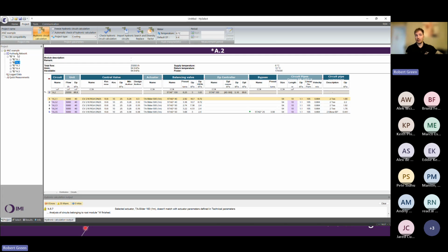Open those 2, close another 2, and prove again. At that point, you've proven you can get the correct design flow to all units within a circuit, and proven that the pump is capable of keeping up with the right amount of things in the project.